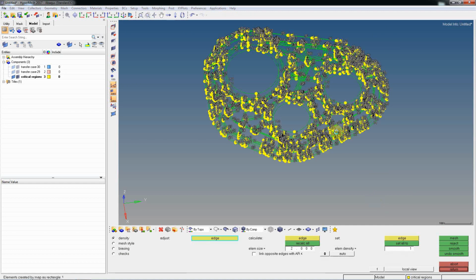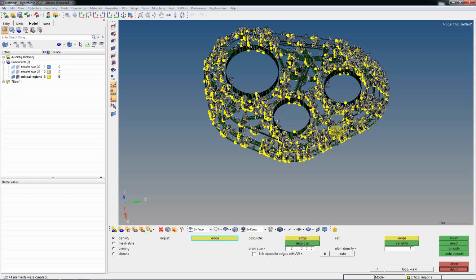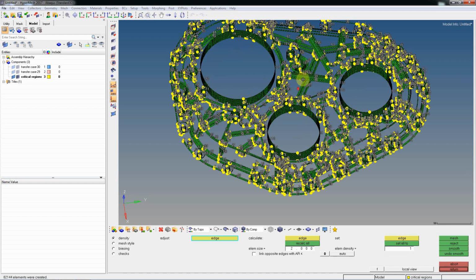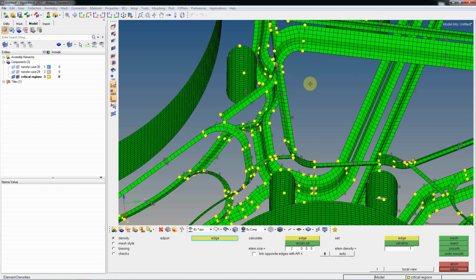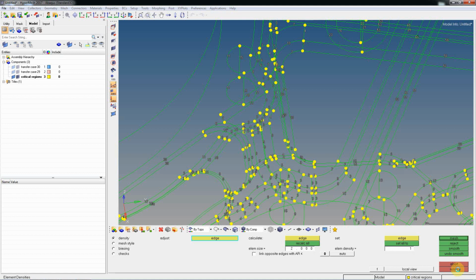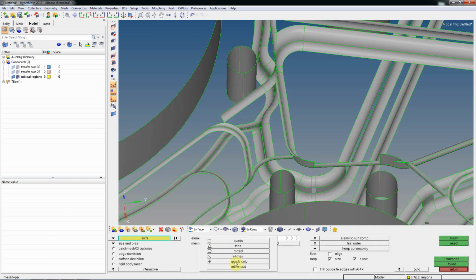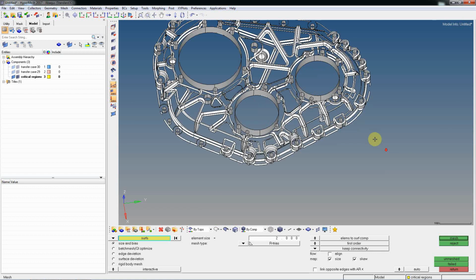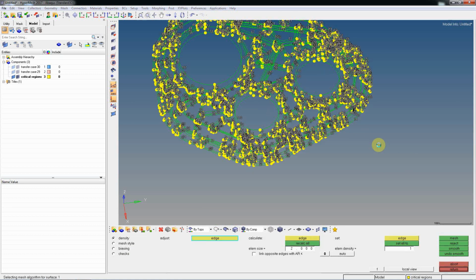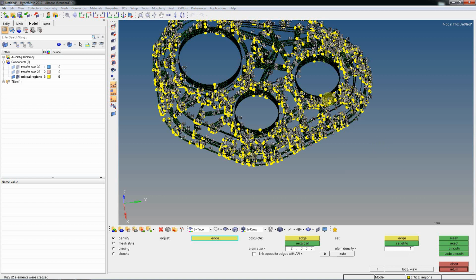So here, majorly what you need to think is, this is the mesh I'm getting, right? In this region I need to put R trias, right? So you can split these things using Shift F6 also, or you can select equilateral trias. You can do it like this also. These are the two approaches, right? So then you got the mesh.